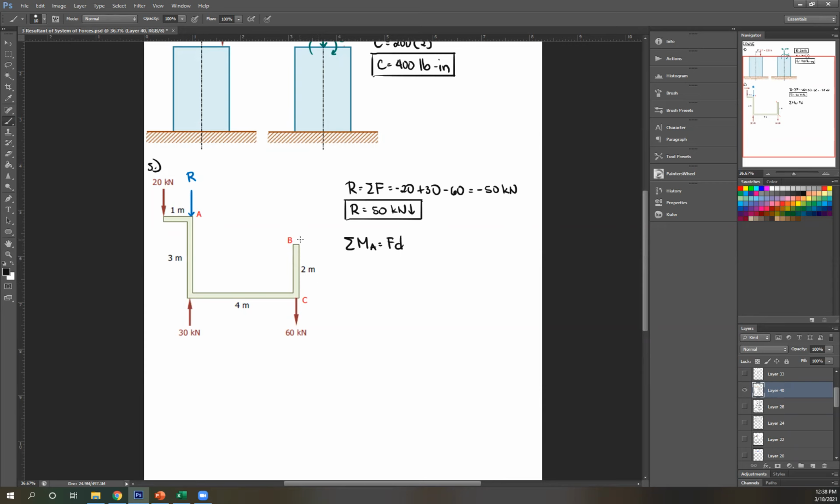So I'm gonna guess it's clockwise. So that would be this way. So that's your F. So therefore, moment at A due to couple F is just F times D. And D is 2 meters. And then positive, since again, I assumed it's clockwise.